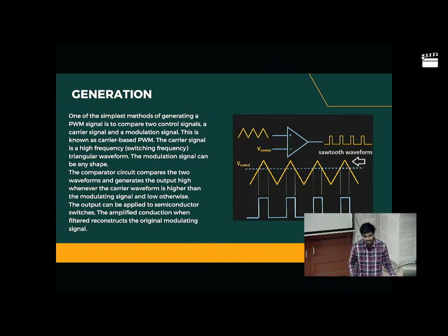Yes, op amps are the correct answer. An op amp is made up of transistors, but this is a different thing. Here the op amp is specifically configured in the mode of a comparator. An op amp amplifies the signal; a comparator is one where the amplification is so high that there are only two levels.